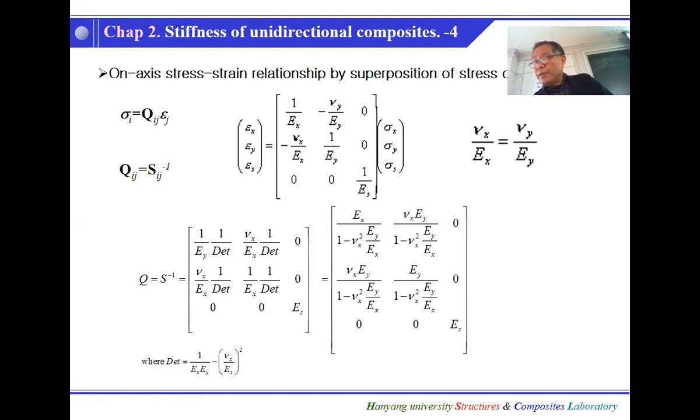Say these are compliance in terms of engineering constants. Of course, a two-dimensional form. So 3 strains and 3 stresses. And now here, 1 over EX and Poisson's ratio mu Y, and Poisson's ratio mu X. In ANSYS, as you saw, it's sometimes called YX or sometimes XY, but we don't need to use those two indices. We just use Y and X.